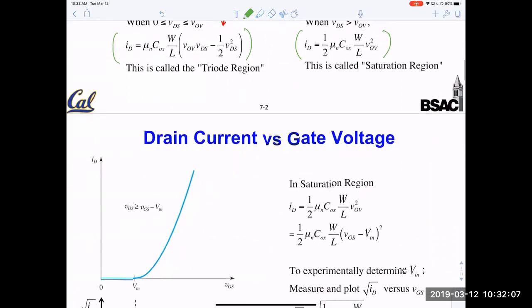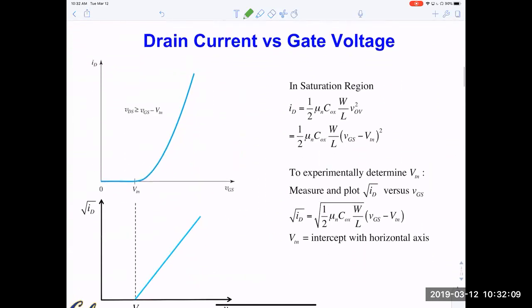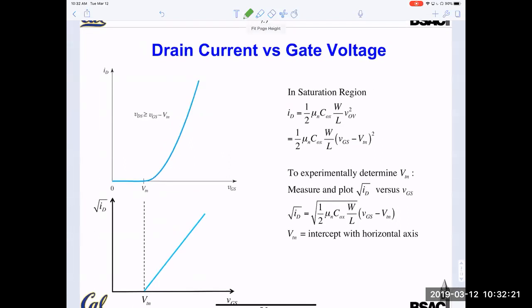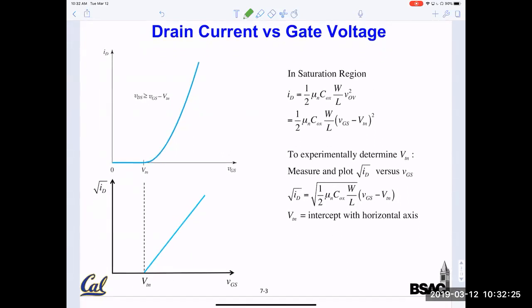Large signal models are not necessarily linear, okay? Like a diode, the large signal model is that exponential expression. That's the large signal model, okay? For the small signal model, we linearize it around a particular bias point, okay? So we talk about the large signal model of ID versus VGS, exactly the same slide we just went through, okay?